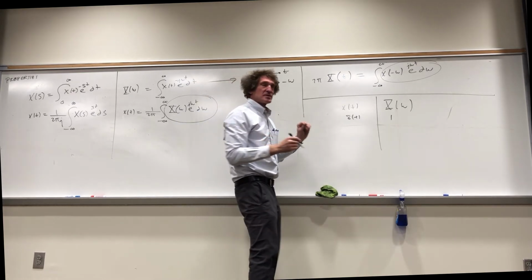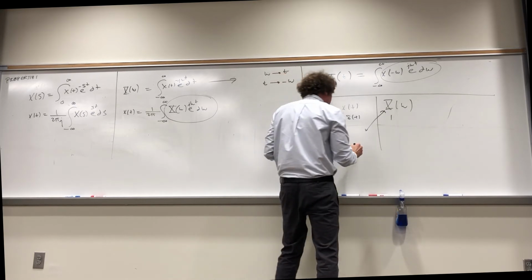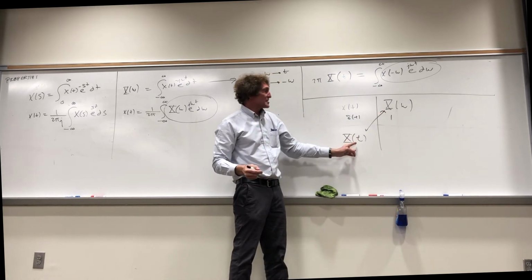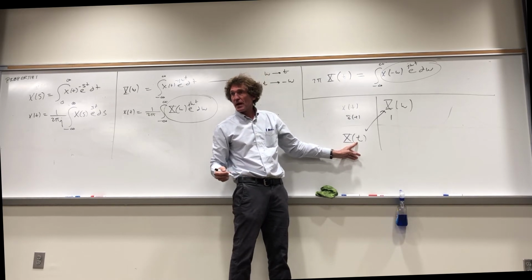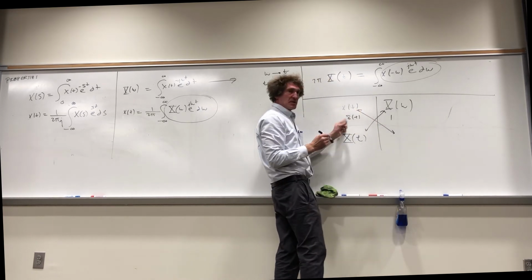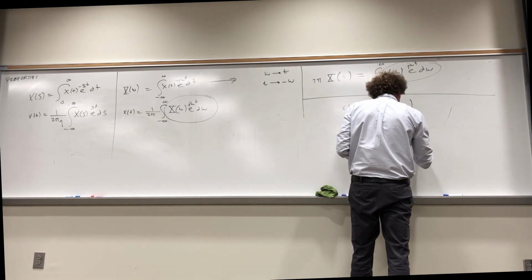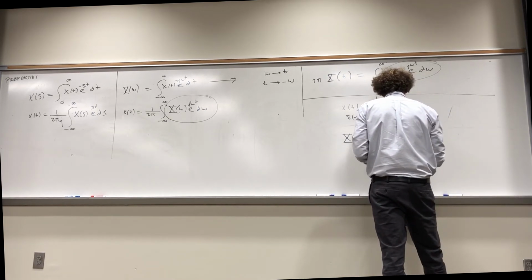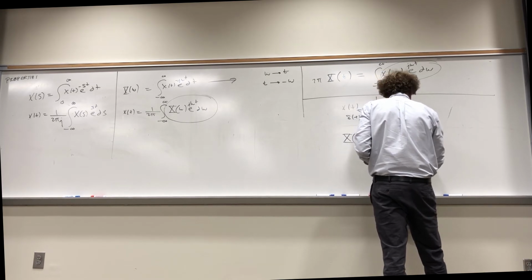Now what duality says, if I take the functional form of this, and instead of omega I put a t, so I put capital X of t here. Say if this is 1, well, replacing omega by t doesn't change. It would just be 1 over here, wouldn't it, class? How many see that? Then over here, you take the functional form of x of t, the delta t, but now you multiply it by 2 pi, and instead of t, you put minus omega. Actually, let me do it this way. It would be 2 pi times x of minus omega.